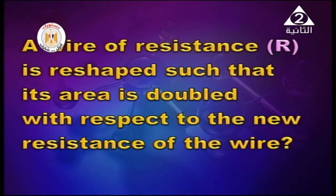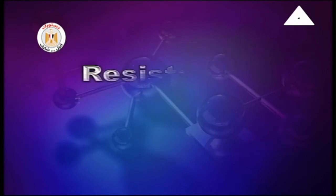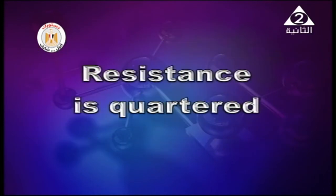Doubling the area will decrease the resistance to half its initial value. Okay, and length being halved will also decrease the resistance. Resistance will be halved once again. So it will be quartered, decreases to 1 over 4.